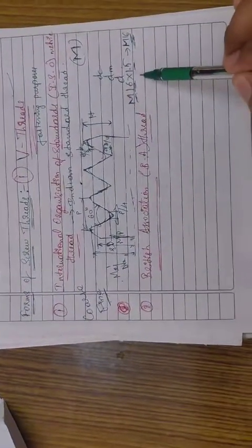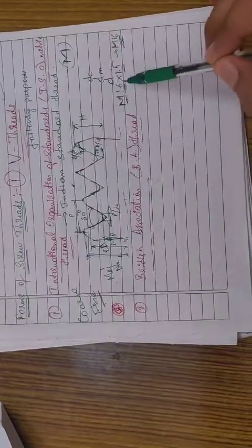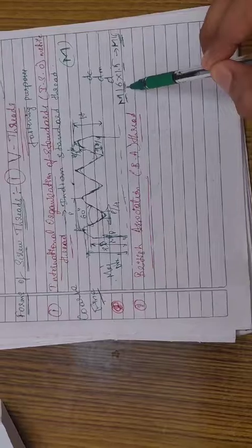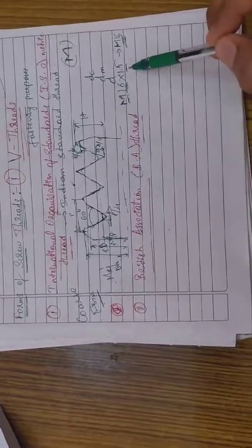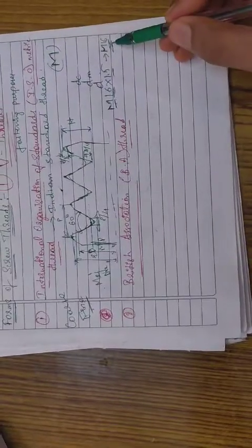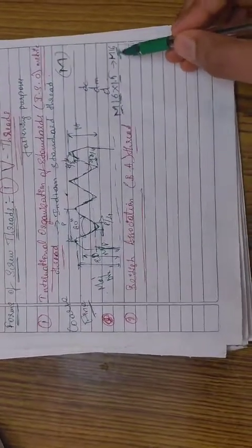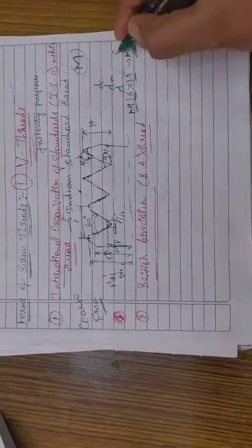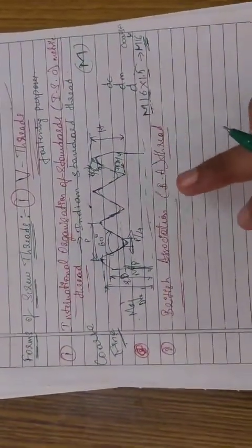The screw thread with a fine pitch is designated with a capital M. For example, M16 × 1.5: 16 represents the effective diameter and 1.5 represents the pitch. If the pitch of the thread is coarse, then the value is omitted and the screw thread is specified as M16. We have to omit it if it is coarse. So this is about the International Organization for Standardization metric thread. Then we will move on to the next one.